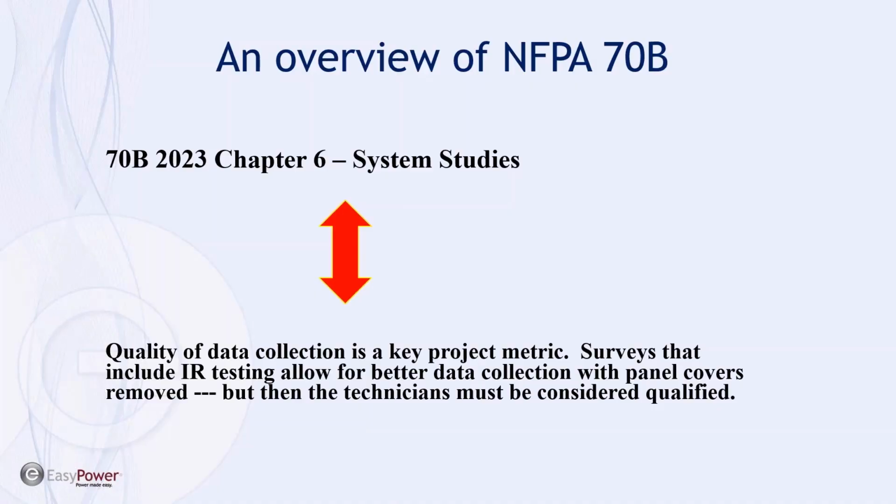So as a result, the quality of data collection means the quality of how those studies are going to turn out over time. And again, the surveys that use IR testing allow you to do better data collection, because one of the requirements of IR testing, which we'll see down the road in just a bit, is that panel covers should be completely removed, which gives you better line of sight to many of the other specifications and attributes of the electrical system that technicians can gather data on.